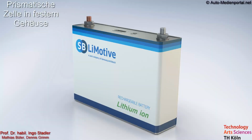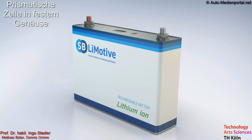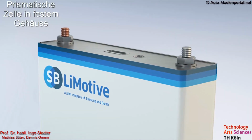Second, the prismatic cell with its robust housing is increasingly used in the automotive industry as well as in home and industry applications. The housing is mostly made of aluminium containing all the cells. In case of overcharging or as a consequence of an internal short circuit, the safety valve opens and the formed gases can escape. From a safety aspect, the prismatic cell is the best one.